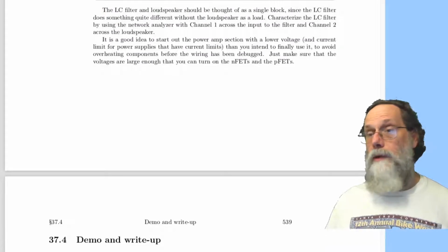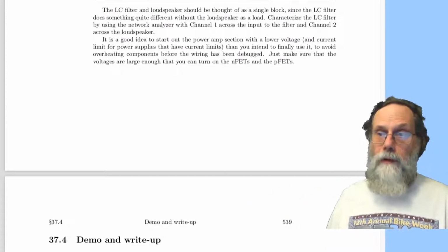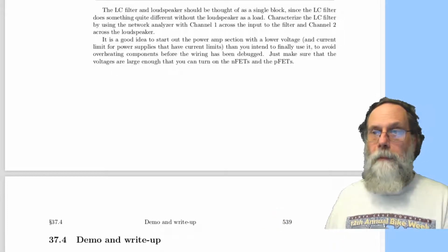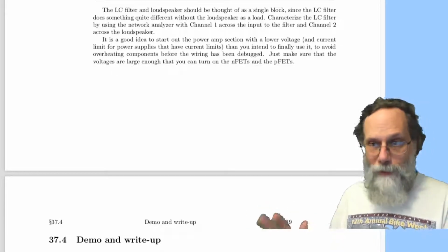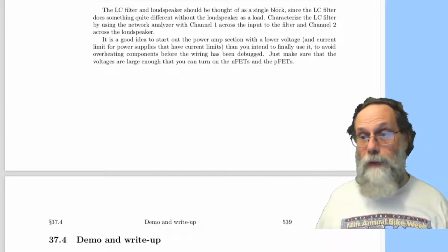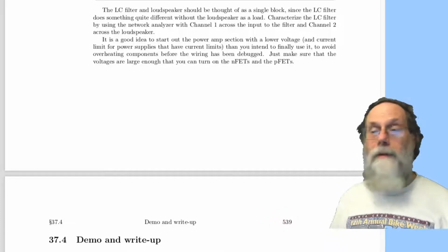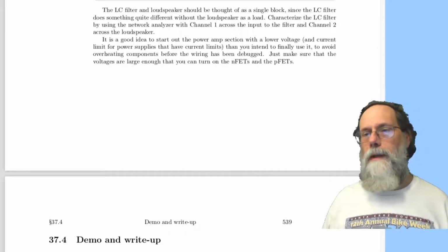Okay, once you've got your PWM signal working, see if you can drive your power FETs with it. Once you've got your power FETs working, if you've got an LC filter there, make sure that the LC filter is working, make sure your loudspeaker is working, sort of build it up one step at a time.